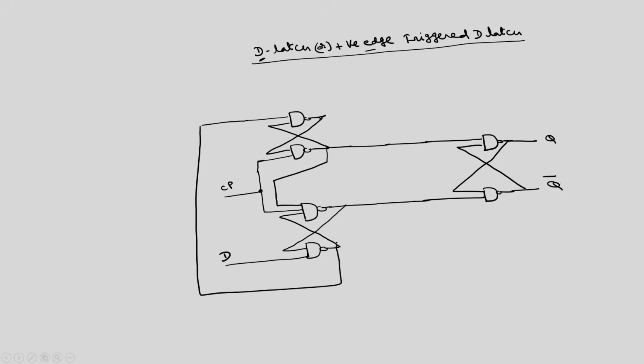So, you can easily verify that this circuit will act as a D positive edge triggered flip flop. You can call this one as not latch, flip flop. So, the basic difference between this latch and flip flop is normally edge triggered means we will call as flip flop, level triggered means we will call as latch. Okay. Now, here we have this circuitry, we have code, this circuitry we have code, this we do not have directly code, but we can derive this code of this one by slightly modifying these 2 codes.